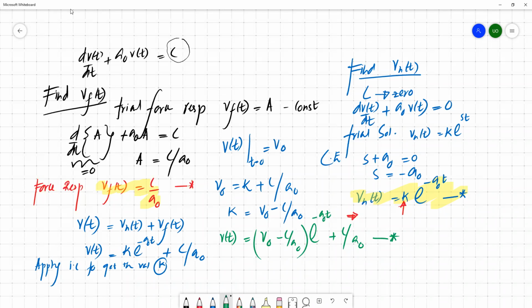So these equations are completely different from the circuit which we are referring. So no point of memorizing those. Start with the Kirchhoff equation, get the differential equation. Once your differential equation has a non-zero constant in the right hand side, then you have to evaluate two quantities. One is the force response of the circuit, which counts the contribution of the external sources.